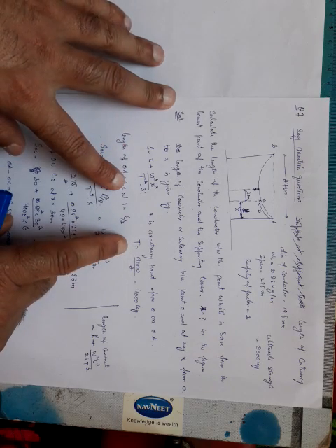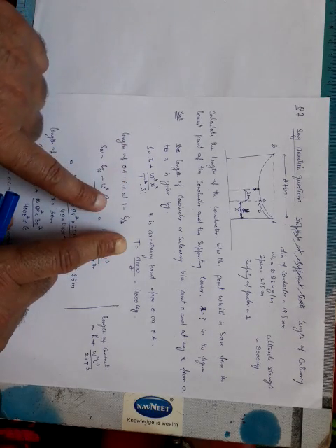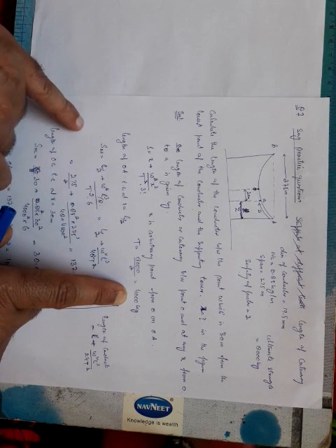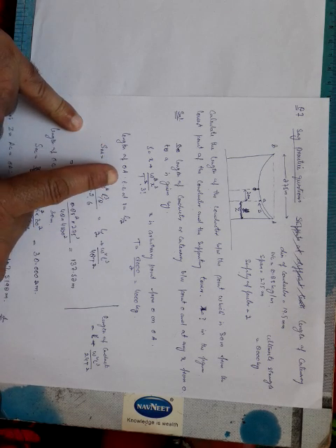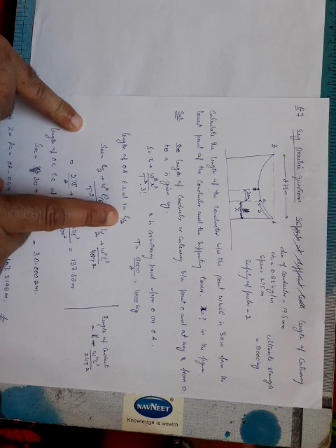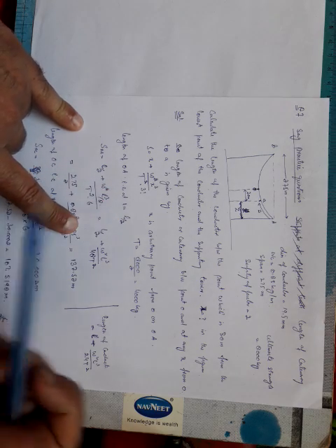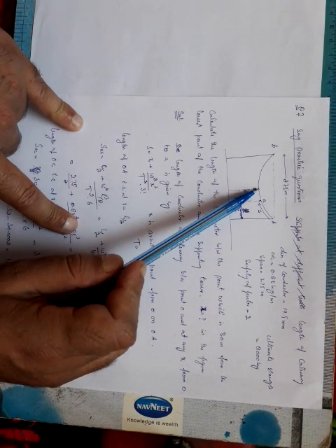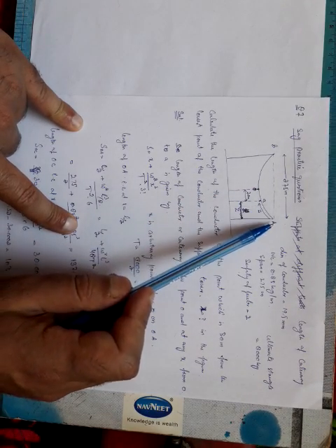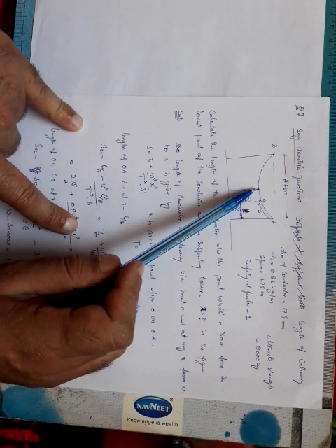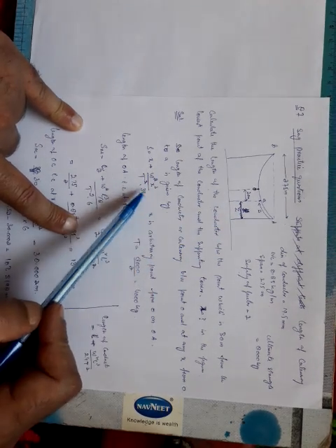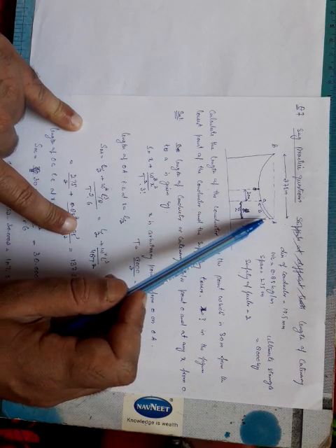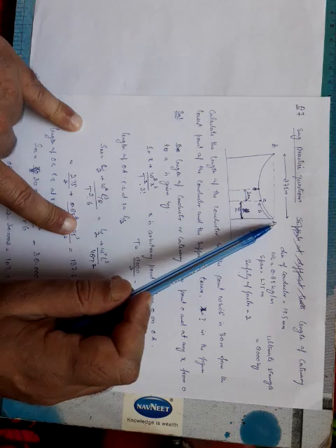Now T is the tension. The required tension will be equal to 8000 by 2, because 2 is the safety factor. It comes out to be 4000 kg. Now the length of OA, that is at x is equal to L by 2, we can calculate first the whole length, then we can calculate the length OC, then subtract them. This equation gives the distance from this point to any other point, but in the question we have to calculate AC, that is the distance from A to C.